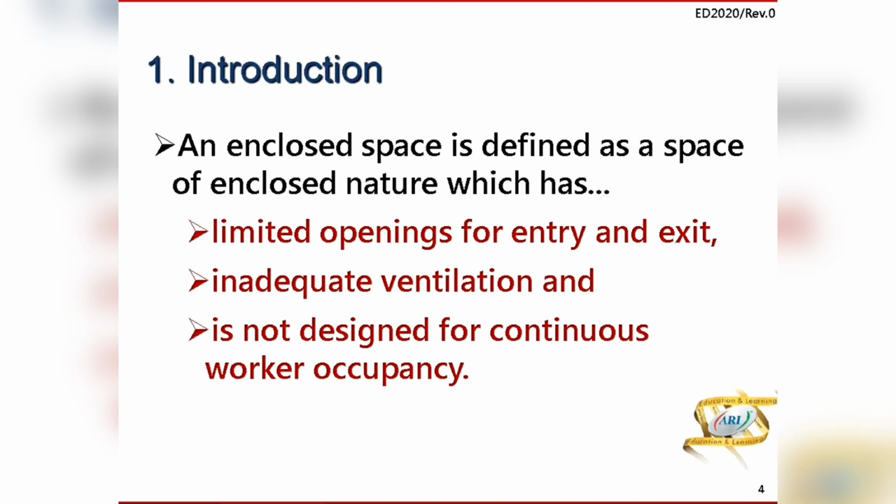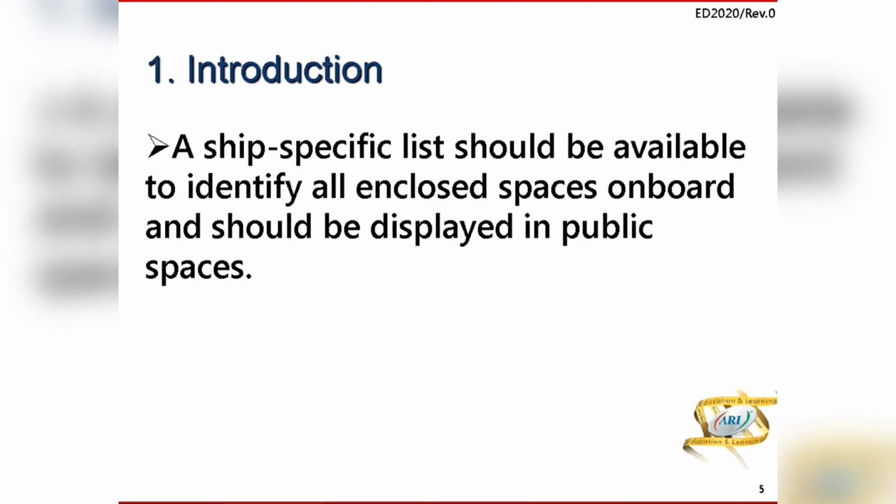It is defined as a space which is enclosed, as it has limited openings for entry and exit. There is inadequate ventilation. It is not designed for continuous worker occupancy. So you should have a ship-specific list of areas where enclosed space entries are required.